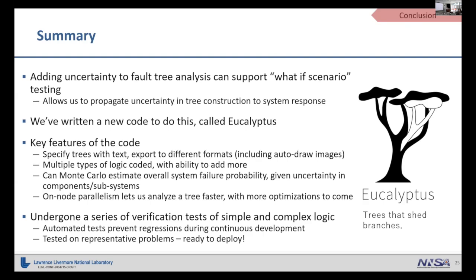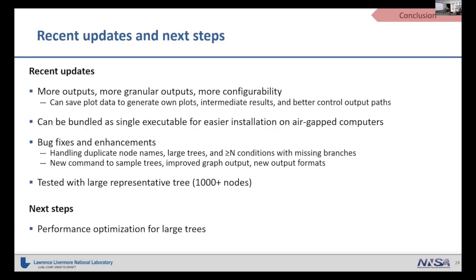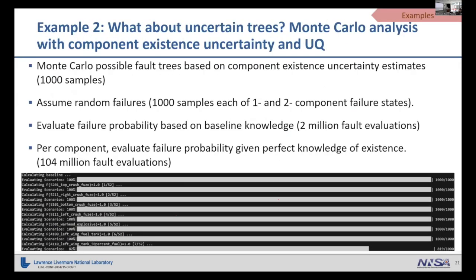So you're using parallel processing on your 4 cores; for a moderate size problem, how long would that take to run? It depends. When you're in Monte Carlo mode and you don't know the answer to the problem, you don't really know how many samples you need for convergence, so it's hard to say in general. If there's a system that you really needed to know the answer to, you would have to do a convergence study like anything else.